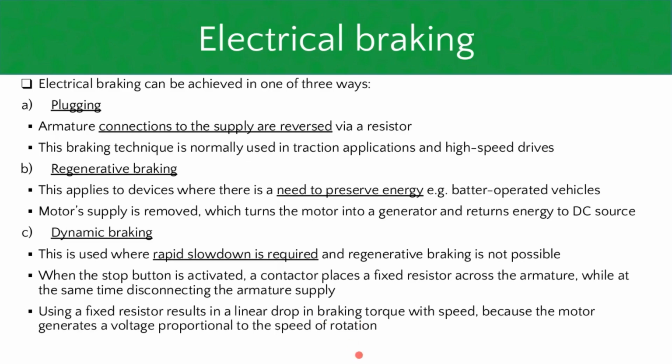And then there are different types of braking. You get what we call plugging. Some of this is actually more applicable to DC machines, like plugging, for instance.